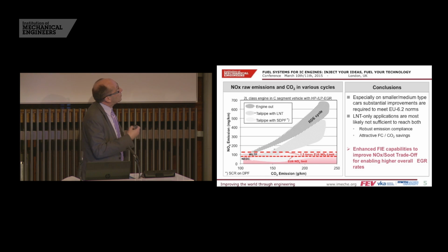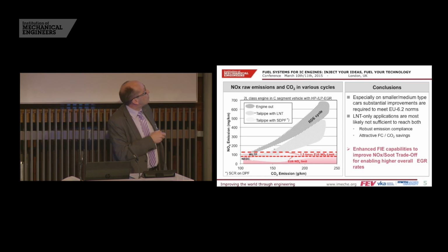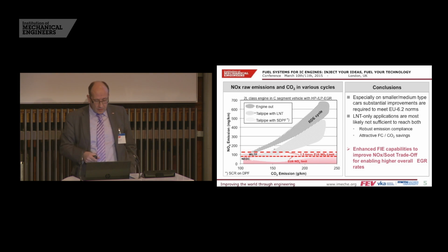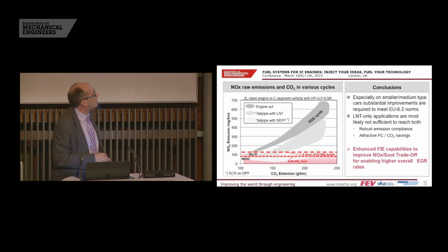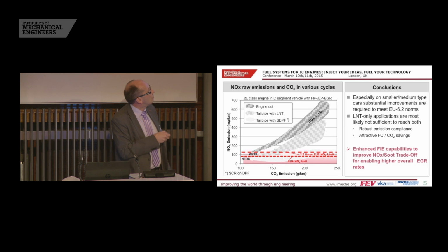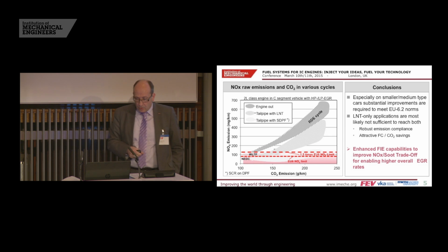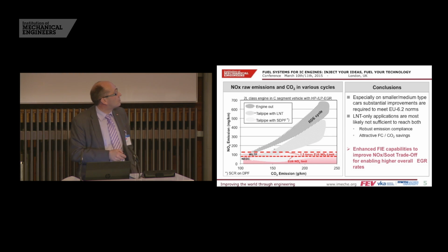Even if we consider a slightly larger engine, we see that with increasing weight, here reflected by the emitted CO2 emissions of a certain application, the distance to the target which we have to reach for such a configuration with a passive SCR system, a very cost-effective solution, will most likely not be able to meet the requirements under the latest status of discussion.